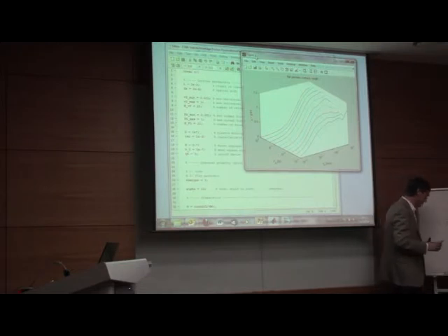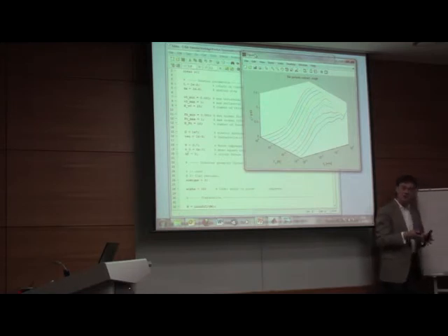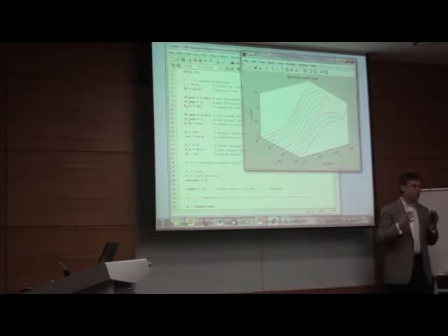But first of all, I would like to say that for rubber, this dependence, mu as a function of v, goes as beta logarithm v. So we can see this region. It looks like this one. This is typical, and this is about 1, and this is about 0.1. This is the true static friction of rubber, and this characteristic velocity is 100 millimeters per second.